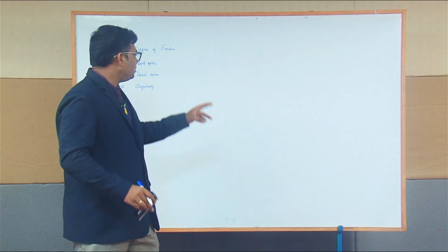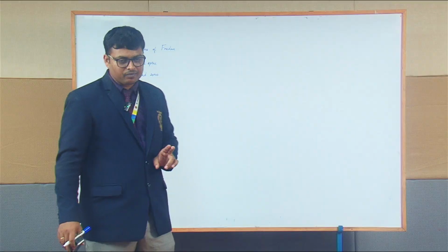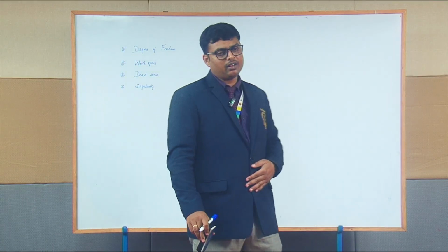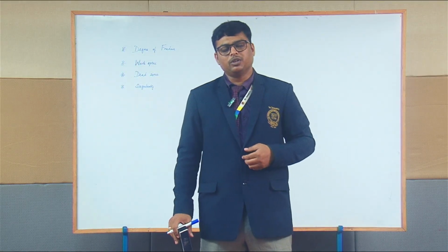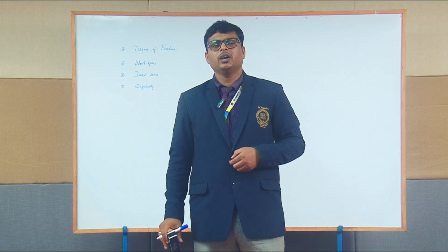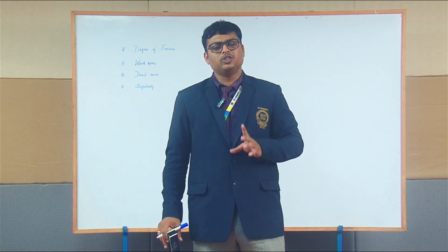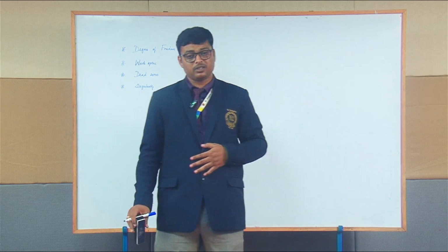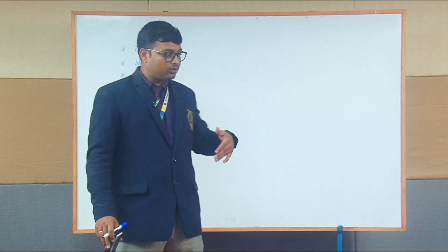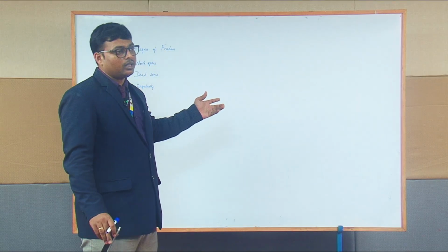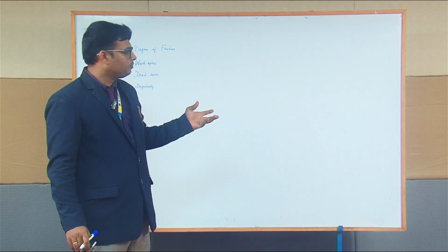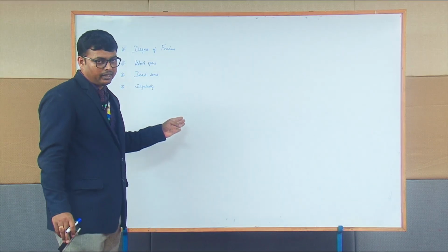All comes under dead zones and followed by a condition called singularity. Singularity is a good term that needs to be understood. So, singularity is where at least one of the joints fails and becomes immobilized, which again goes to a dead zone part where the robot loses its degree of freedom. So, possibly you might have understood things.